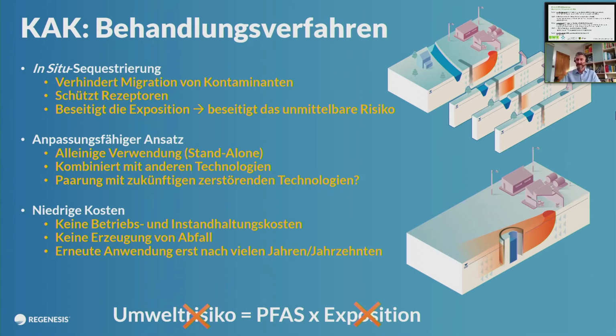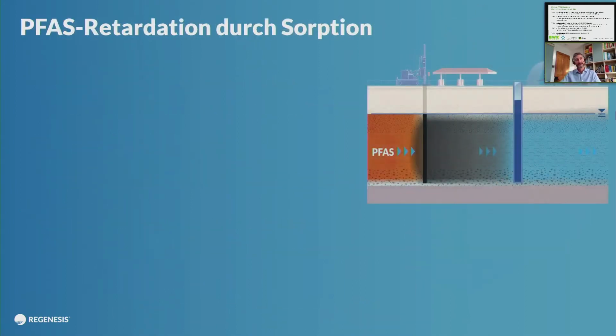So nothing's going to landfill either. There's no cost from waste. So retardation, it's a dynamic process. What you're actually doing is slowing the contamination as it moves through the subsurface, but it's an extreme form. We are slowing this contamination dramatically compared to how it would normally flow through the subsurface.